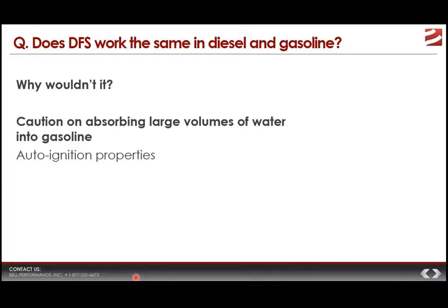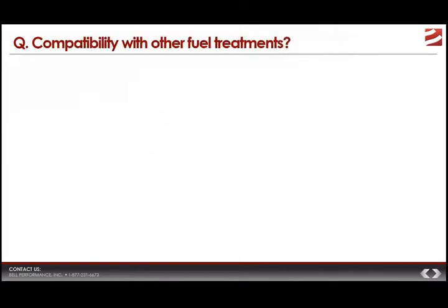The only thing you would want to keep an eye on is, if you're using it in regular gasoline, make sure that you don't try to absorb a large volume of water in there. You can absorb some amount of water. In fact, it's been popular to do since the 1950s even. But if you absorb too much water in there, it can start to play with the auto-ignition properties of the gasoline, which is not something you really want to do.